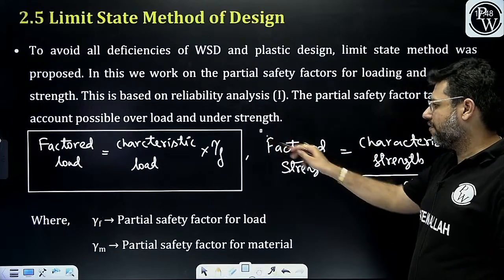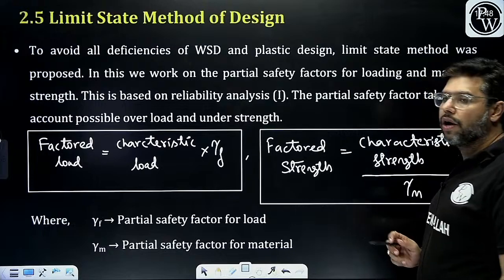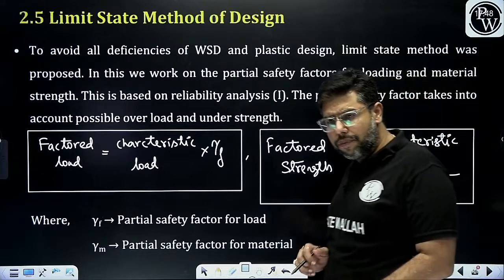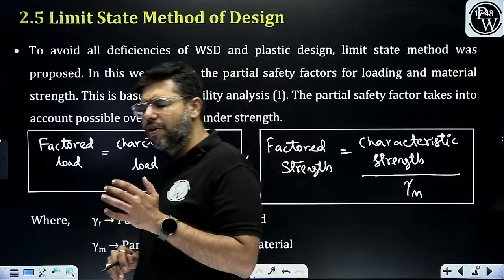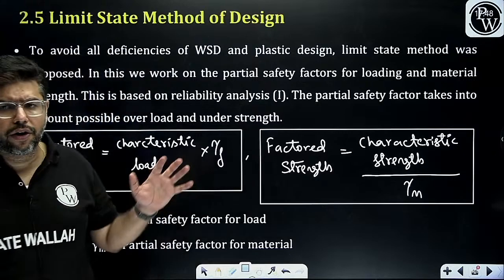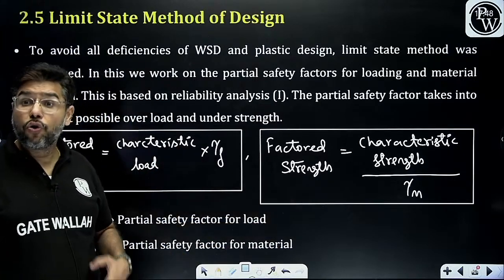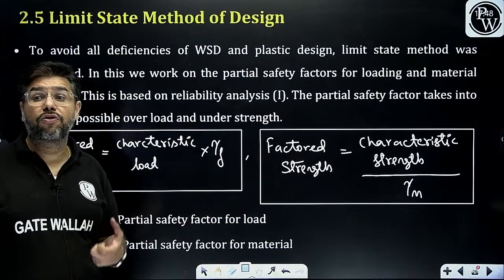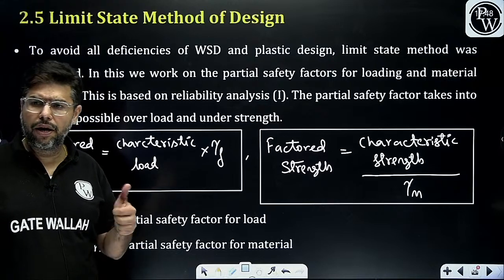When will you be safe? When you increase the load and you decrease the strength. So, here the safety factor is introduced both on the load as well as the strength to take into account any possible overloading or understrength. Am I clear till here?